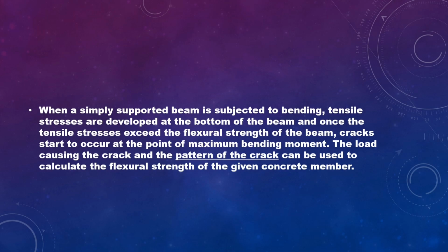When a simply supported beam is subject to bending, tensile stresses are developed at the bottom of the beam, and once the tensile stresses exceed the flexural strength of the concrete, cracks start to occur at the point of maximum bending moment. The load causing the crack and the pattern of the crack can be used to calculate the flexural strength of the given concrete member.